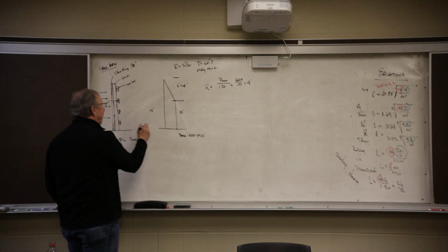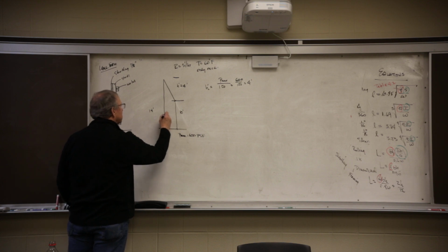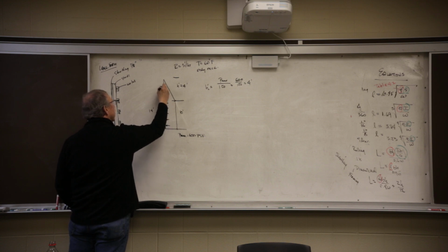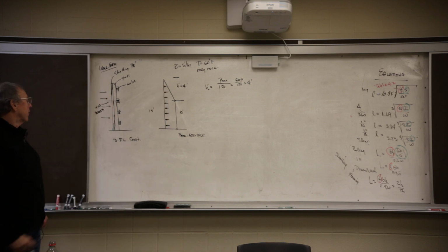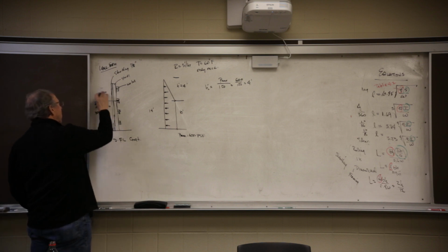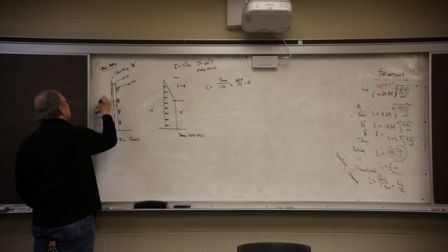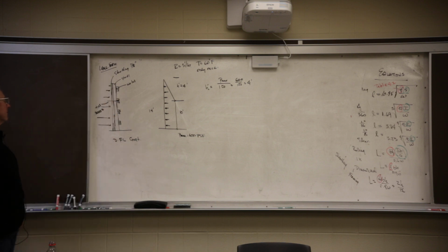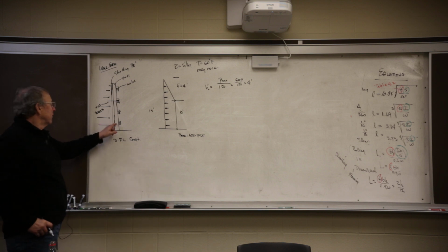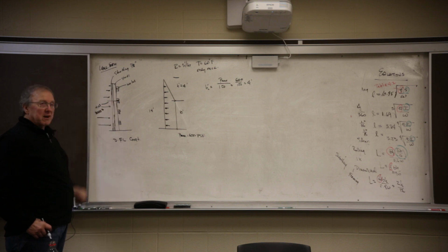So inside the form, you've got this pressure pushing out, and you can see as it gets near the top, the pressure becomes 0. So right now I've got pressure pushing on this wall, and I'm going to make these long, make that a little shorter, a little shorter, a little shorter, and nothing. So it keeps getting smaller as I go. Now, we've got 4 elements: sheathing, studs, wales, and wall ties.